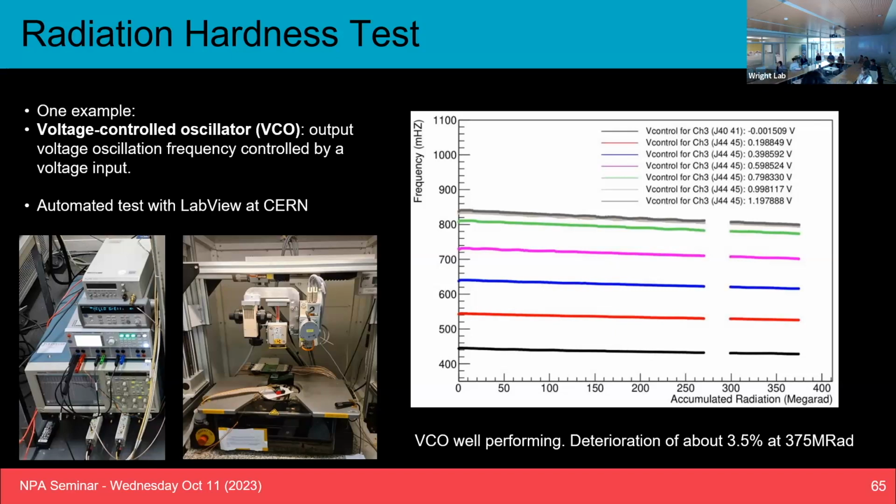And then you're setting it to a constant voltage and seeing that. Actually, it does a scan of the voltage. It ticks through and scans, and also takes a measurement of its frequency with the oscilloscope automatically. So it just records the data. We don't have to be there and change it by hand.